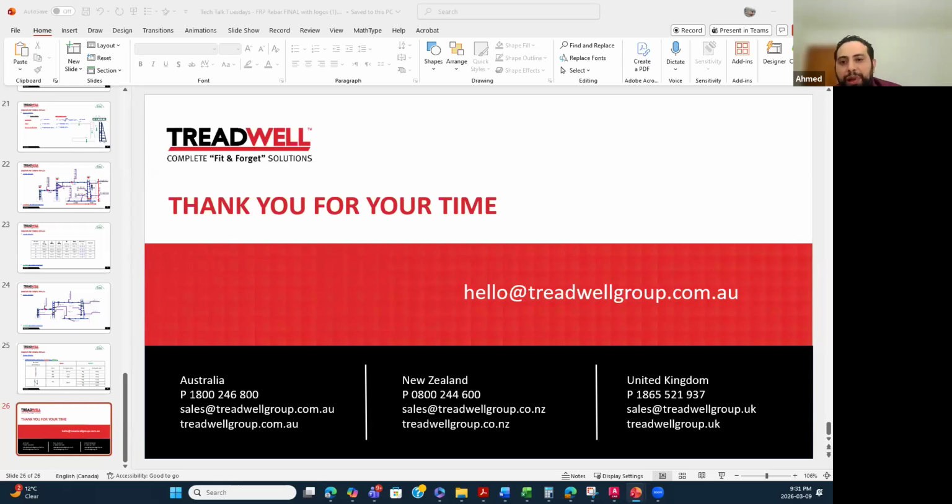For design performance compared to Eurocode, as I mentioned, all FRP codes have the main assumption of design for FRP bars, but there are some differences, including the ultimate strain of concrete, the assumption of mode of failure, and how we can adjust for the failure, whether it's compression failure or tension failure. But Eurocode, ACI, CSA, and any FRP codes have the same assumption.